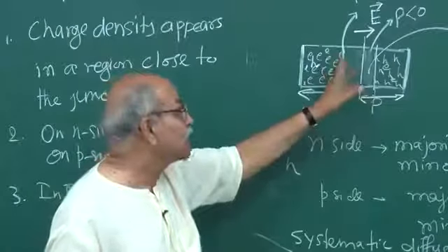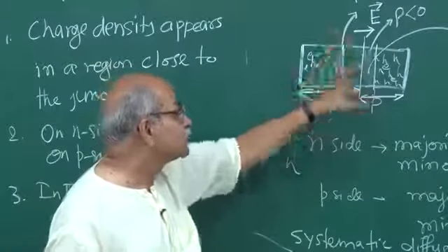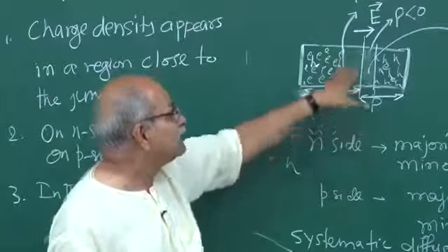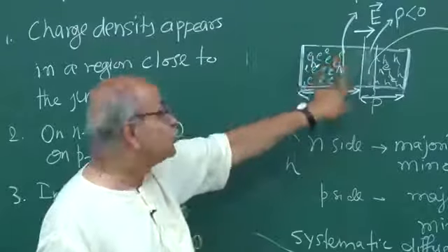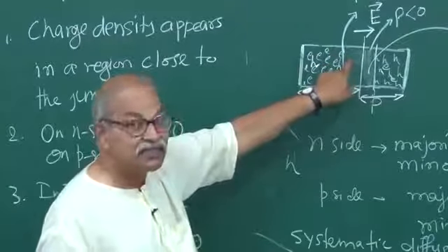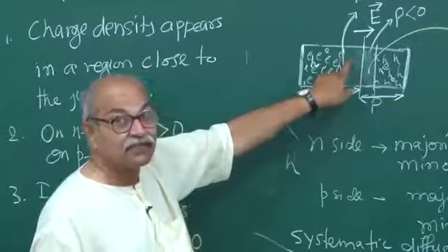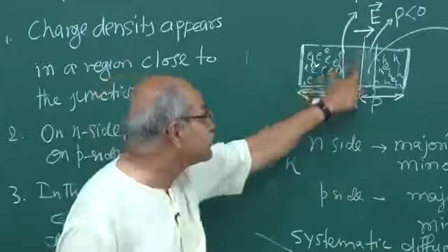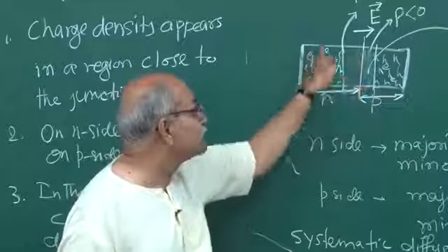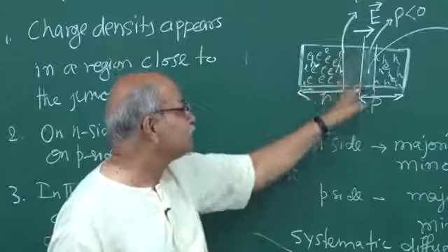So although the charge carriers are not there, the conduction electrons are not there, the holes are not there, still those pentavalent impurities that we have put in, arsenic or phosphorus, they are still there, distributed in this entire region. This is still N type region.